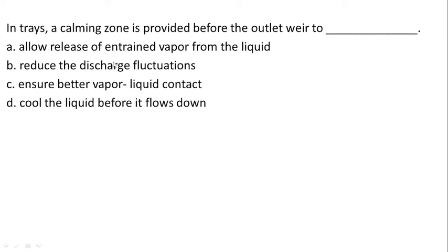And velocity is also given. We can divide the total flow rate by the velocity to obtain the area. First we will find the area, then from there we can find the diameter. So the diameter of a distillation column is based on flooding condition, not on weeping condition.